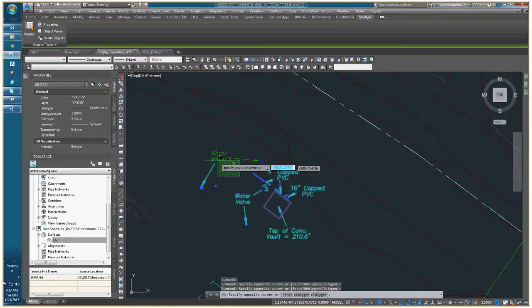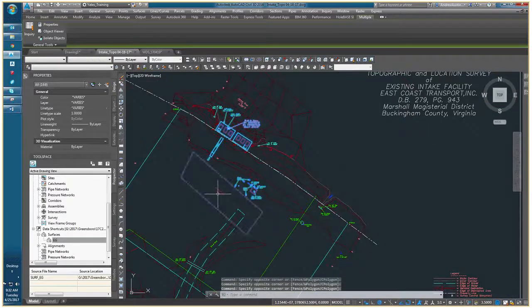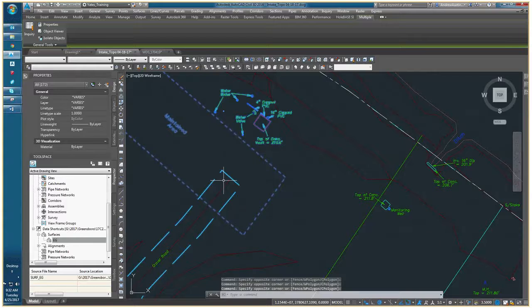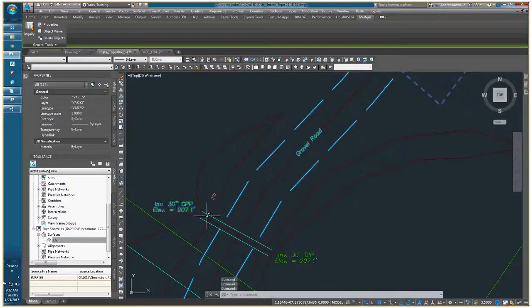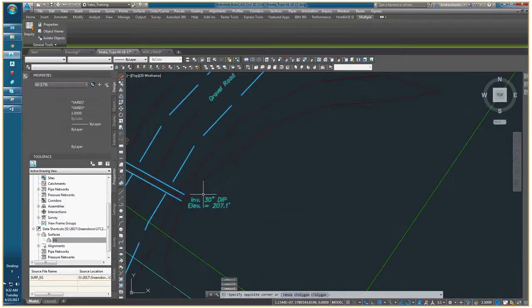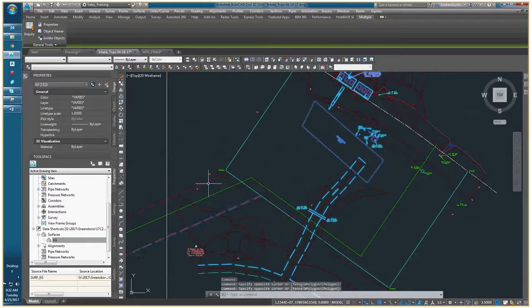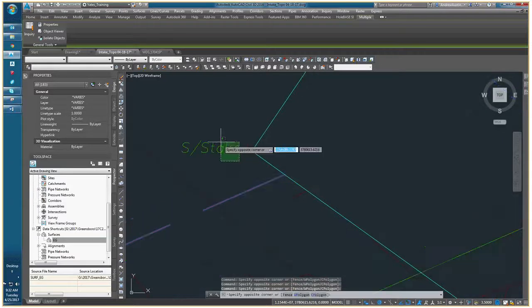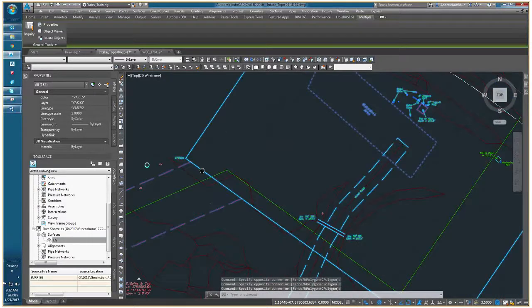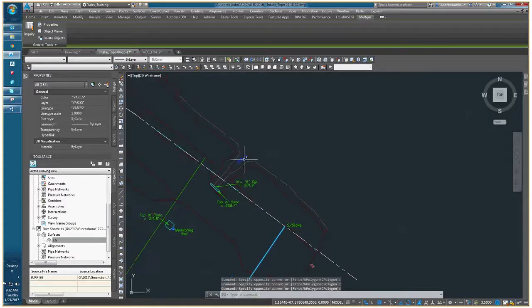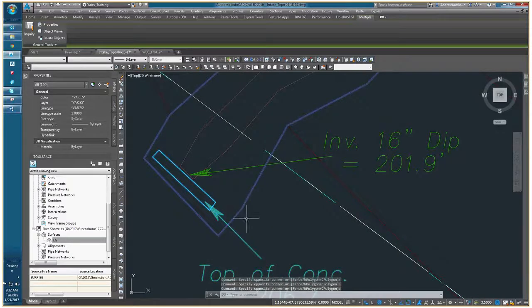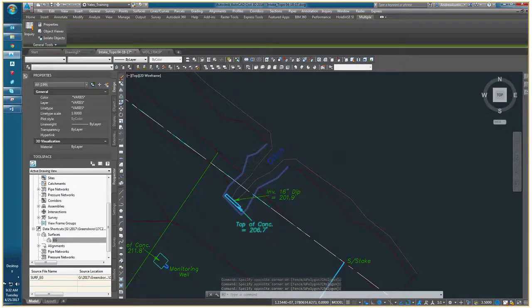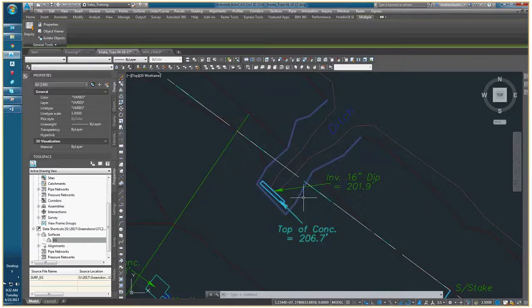So we're grabbing individual components of this survey carefully and methodically, text and line work that has pertinent and important data for our needs. But we're not grabbing everything. We're grabbing most of the important stuff. Here I inadvertently grabbed one of these red survey lines. I think these are break lines in his surfaces. But I'm going to shift and select it again to deselect it.